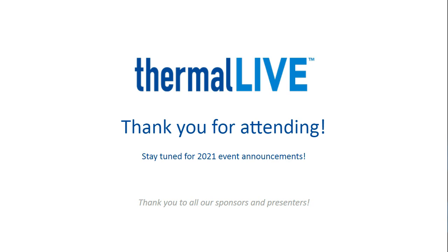Okay, well, we have a question here. How good is the jet impingement heat transfer? It's a good question. Jet impingement heat transfer is and can be extremely efficient. In fact, it can be even more efficient if coupled with a phase change. So if you are impinging a saturated fluid onto a heated surface, you get that added benefit of the momentum of the fluid removing heat from the surface as you impinge down on the surface, and then the latent heat absorbing that energy of the working fluid and then creating vapor or two-phase fluid in the downstream can be an extremely effective way to cool very high heat flux components.